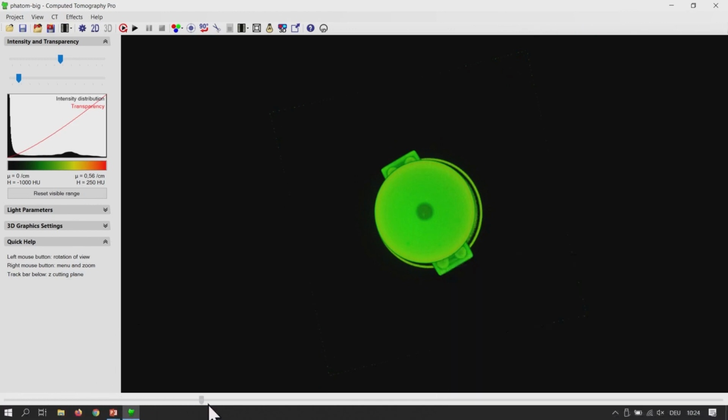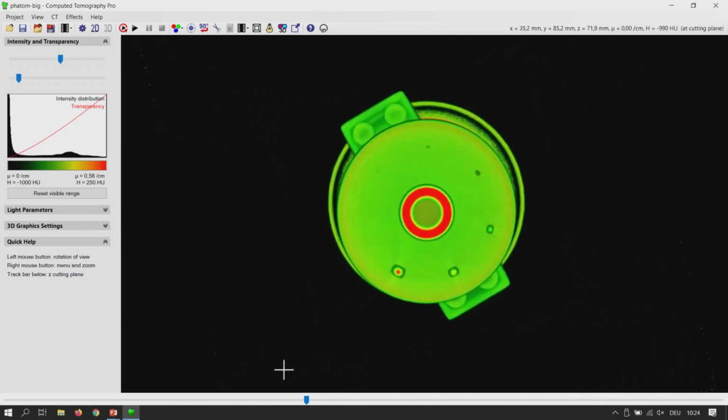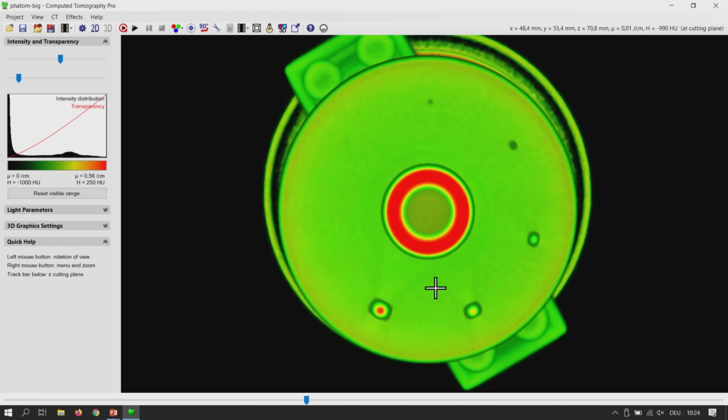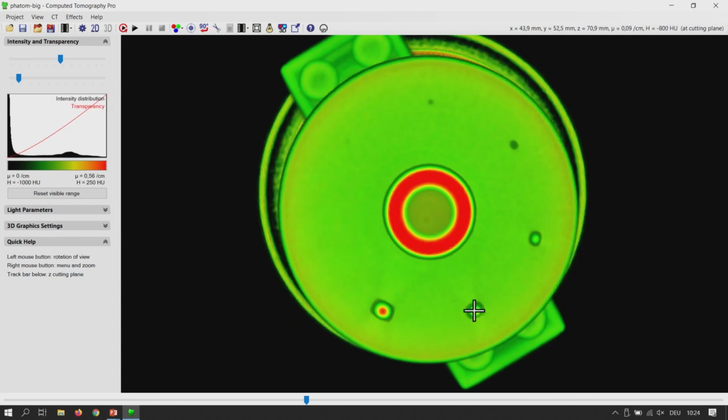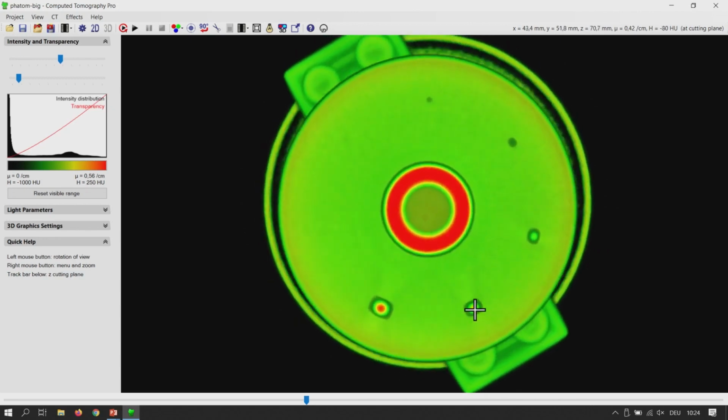And we'll cut off the top layer. And here you see all those tiny wires. Can zoom in a little bit. And now you see we have a large diameter wire and succeeding lower diameters, and the last one right here is barely visible. So we have already reached the resolution limit of our CT setup. And now students can start to calculate what is, for example, the dimension of this. It's 2.1 millimeter, but these are just artifacts around it, and the wire diameter is something like 0.5 millimeters.